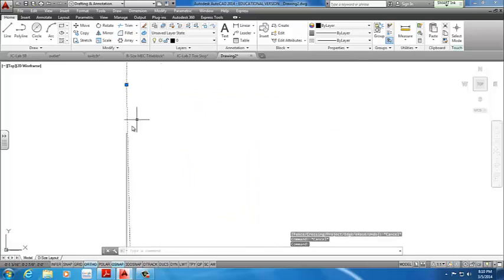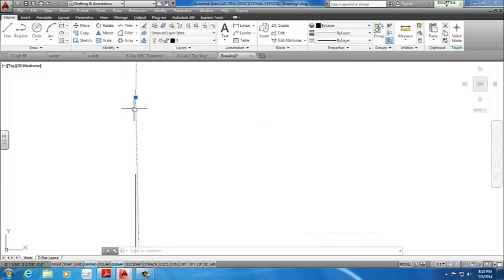Something happened. Go to here, trim, select the entire object. No, it got moved. The end line is right here, and my quadrant is here. Should have not made it perpendicular. Should have actually made sure that I was hitting the end point. These things happen. This is how you catch it. So I'm moving it again. Move command from that quadrant to the end point. Now you can see it specifies end point.